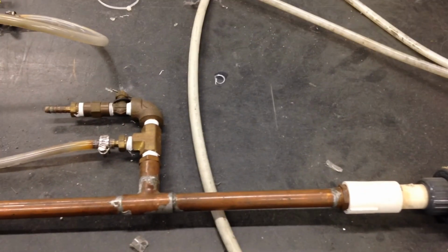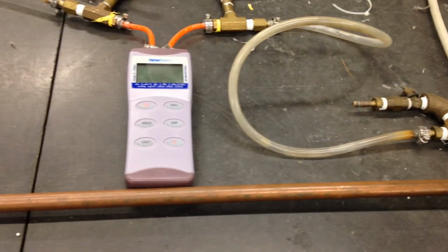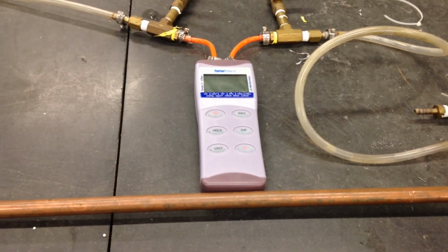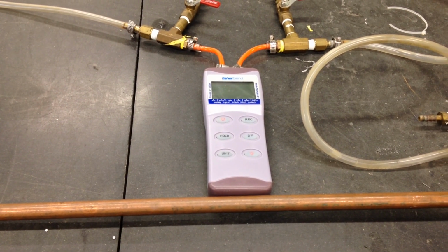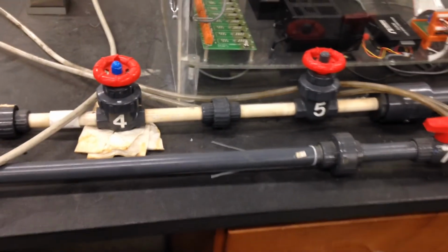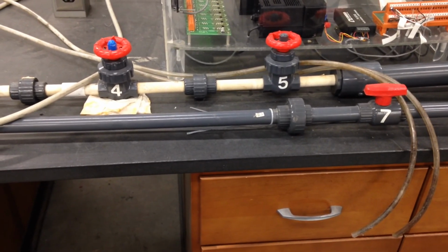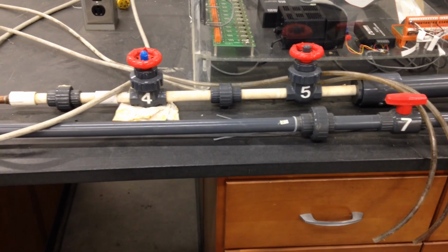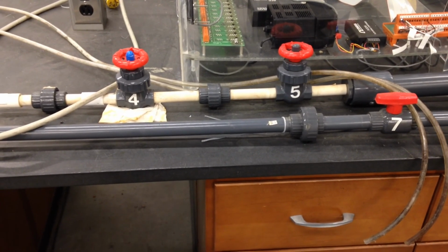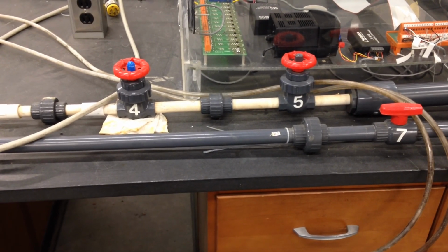This is the one place where we'll find out for different flows what the loss is in this piece of pipe. And you'll be able to correlate that and see how well it matches the Moody chart. There is one important thing to do. For the first two experiments, we have these three valves. Valve 7 is open, and valves 4 and 5 are closed for the flow meters and the gate valve. For the Moody chart, the pipe losses, 7 is closed and 4 or 5 are open.